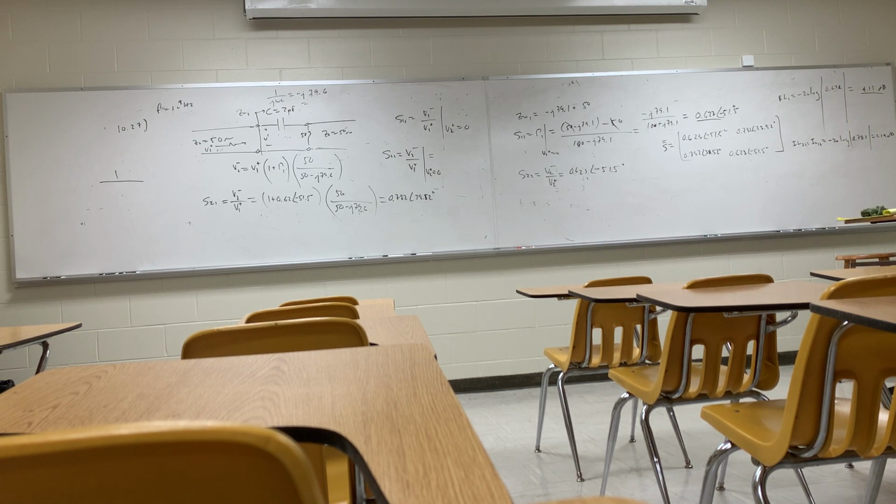When you look at this, just listen to me now. Does everybody have access to the book? Take a look at the first one, 2 straight things. If it's 2 straight things and there's a matched load, what would S11 be for that one? Is there any reason for reflection? If you got 2 straight wires, that means Z0 is coming from Z0. So the input impedance is Z0 to that port 1, same as the impedance you came from. Reflection coefficient is 0. S11 and S22 for the first one, that's A, is 0.